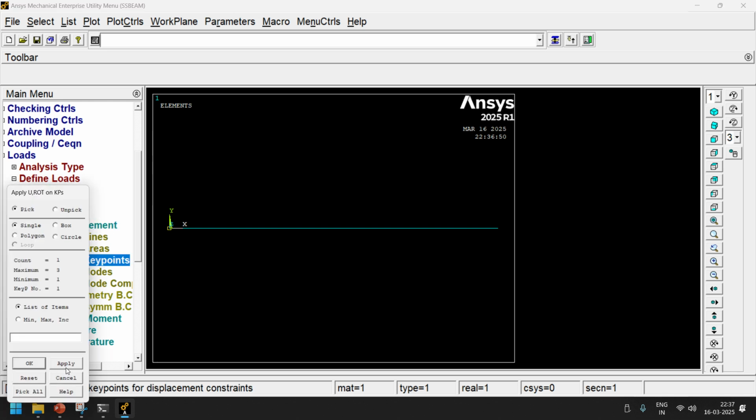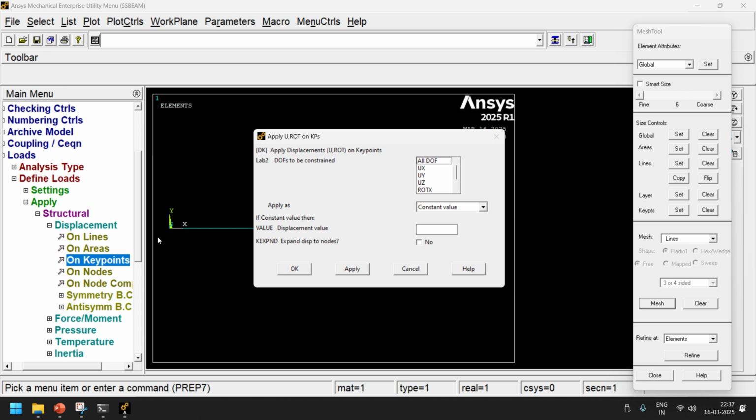First this point I am picking it. So if it is the pinned end, there is no translation, and rotation also, or it will be rotating only about this z axis. About the z axis alone it will rotate. So other things we have to constrain. Okay, so pinned end means it can rotate only about the z axis.